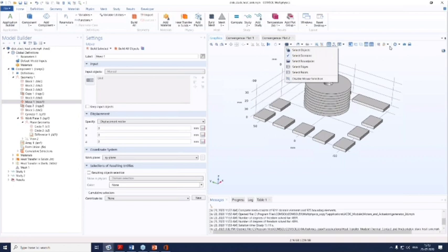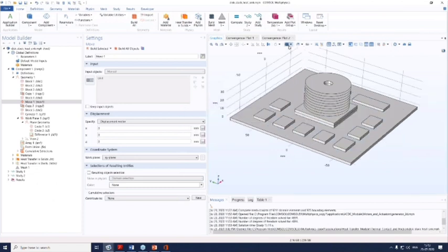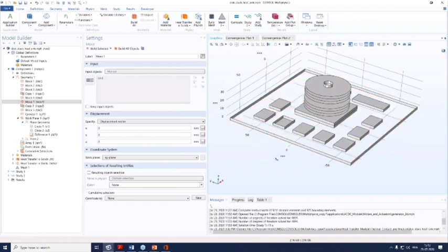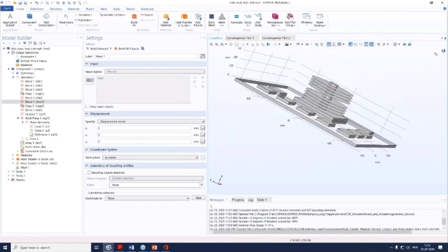Now I can just reset hiding. I can click on this button and do the reset hiding. Once that is done, if I want, I can also select some boundary, and over there you can see that any boundary can then be selected. This is how the hide and unhide option works. In order to come out of this hide option, you just need to click on that button again. That is kind of a toggle button that we are having.